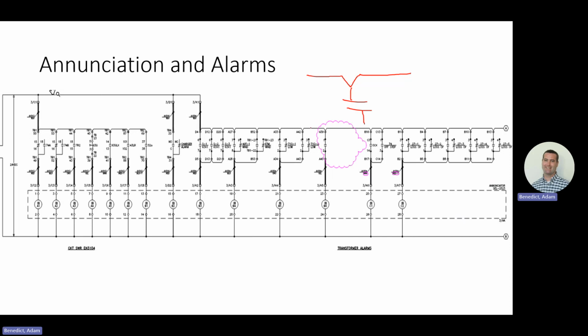So if I were to see a schematic like this, I would think, all right, we're going to wire from B52 to A33 across to A42 to A39, which isn't the best way to wire this at all. In this instance, you'd rather go from A33 to 39 over to 42. So I guess be cautious of using this unless the client specifies that.